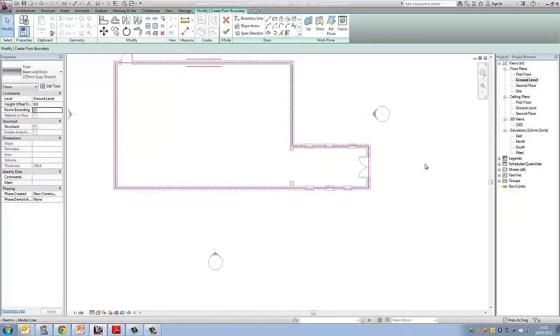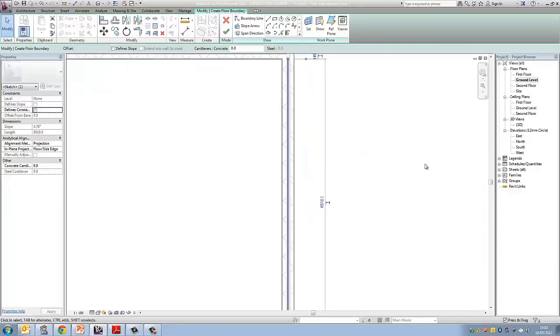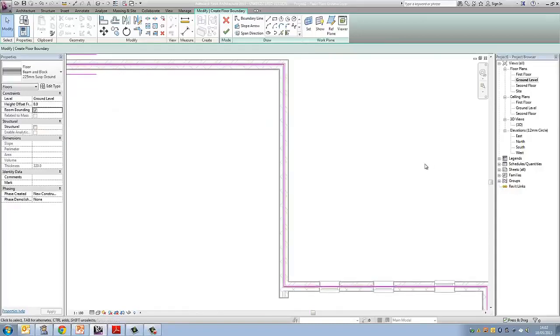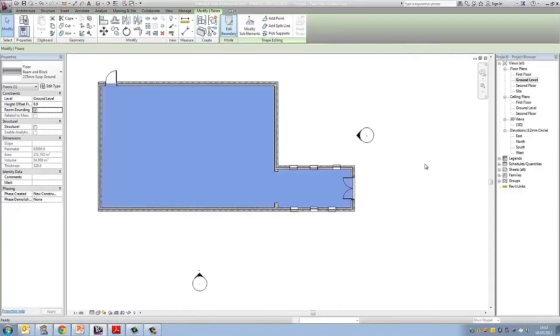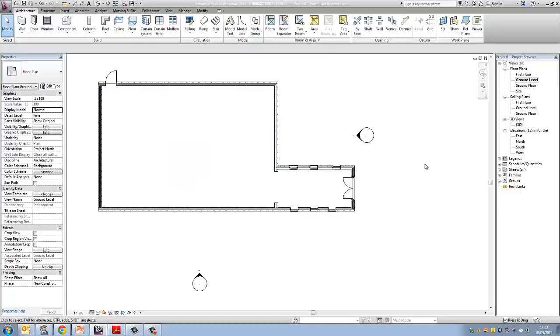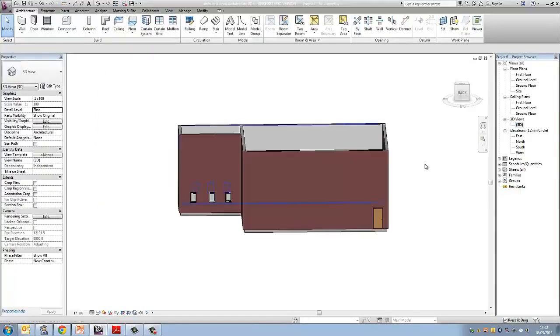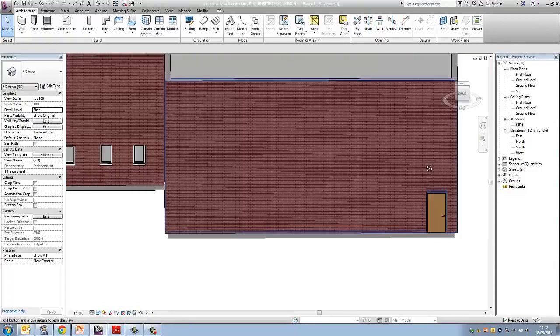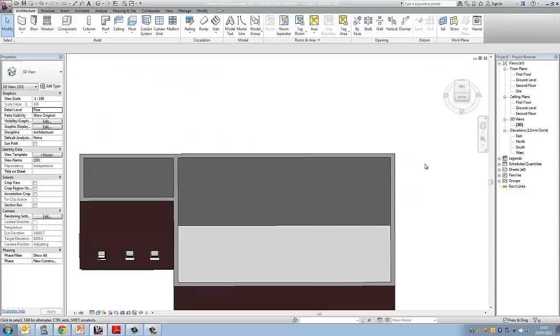As you can see, there was a problem here, over in the top right, they aren't connected. So just drag and connect it with the pink square, and it's all connected. Click the green tick, and there you go, you have your floor. If we go to the 3D view now, you have a floor here. If we look inside from above, you can see the floor there.